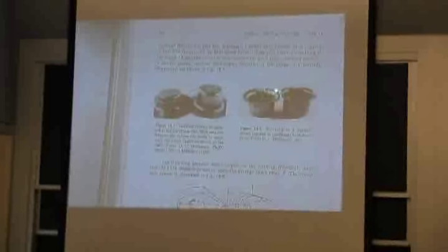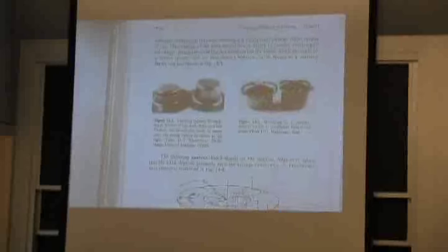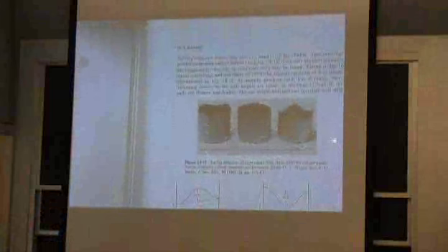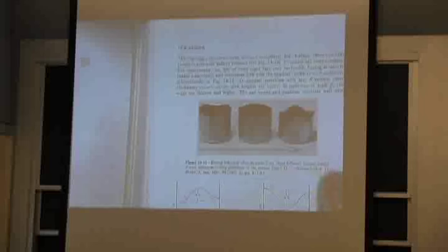So here's a failure at the bottom of the cup. Here's wrinkling. You didn't have enough pressure holding these down, and so up here where everything's going into compression, the cup wrinkles on the flange. Here's one where you get earring. This actually comes out of Hosford. This is another one from Hosford, an earring example. These are copper sheets, okay? So earrings are a problem, and so we will continue on.